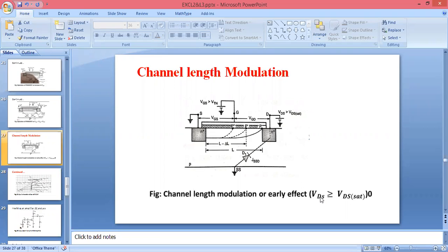The junction between drain and substrate becomes more reverse biased. Therefore, according to the rule, the depletion region on both sides should increase. On the channel side, since pinch off means saturation region, the pinch off cannot be shifted upward, because there is a SiO2 layer, so it gets shifted towards the source.